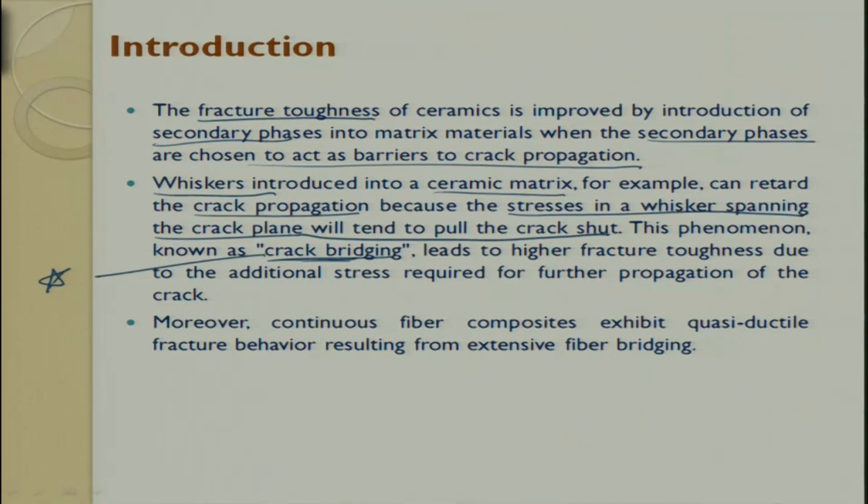What is this phenomenon? When the whisker is introduced into the ceramic matrix, it can retard the crack propagation, because the stresses in the whisker spanning the crack plane will tend to pull the crack shut, and this is called crack bridging, which leads to very high fracture toughness.